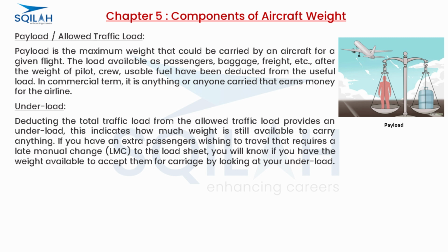Underload. Deducting the total traffic load from the allowed traffic load provides an underload. This indicates how much weight is still available to carry anything. If you have extra passengers wishing to travel that requires a late manual change, LMC, to the load sheet, you will know if you have the weight available to accept them for carriage by looking at your underload.